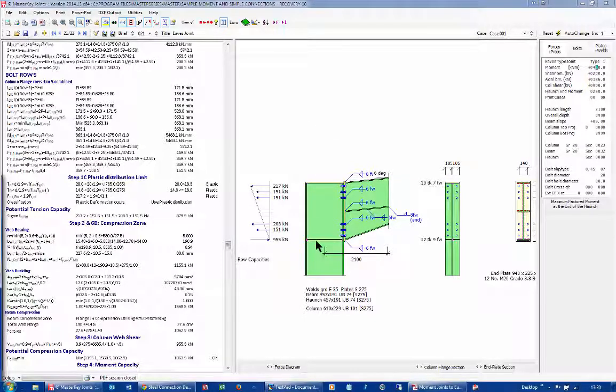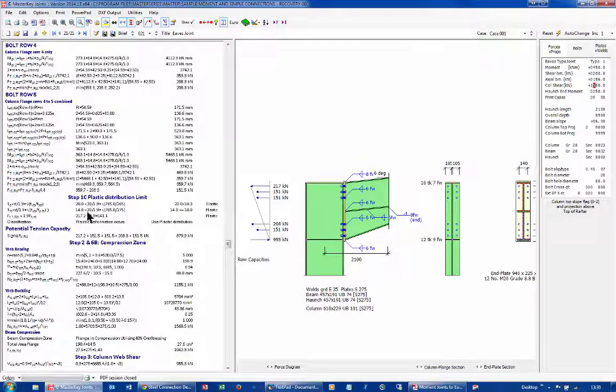Now we are. So if I was to say there is a column axial load of 200 coming from above, it can actually suddenly start to modify my capacities. Obviously it's very insignificant. If I put this up to say 500 or 1500, now we're beginning to get some changes in our values. But this is, sorry, that's column shear, I apologize.